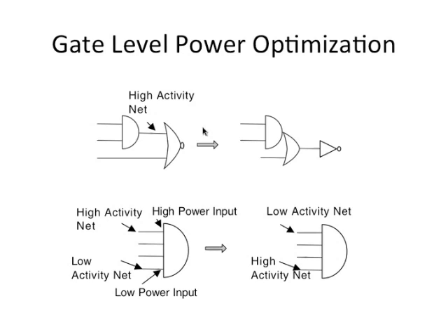Okay. So another kind of simple optimization is, say you have a logic circuit like this. You have an AND gate followed by an OR gate. And if it turns out that this particular net is a high activity net, then instead of using these two different gates in your standard cell library, you use a compound gate. In a compound gate, through appropriate creation of the stacks, the same gate incorporates the AND gate functionality. So when you do that, there is no explicit wire going from one gate to the other, and you are reducing the capacitance and hence the power dissipation.